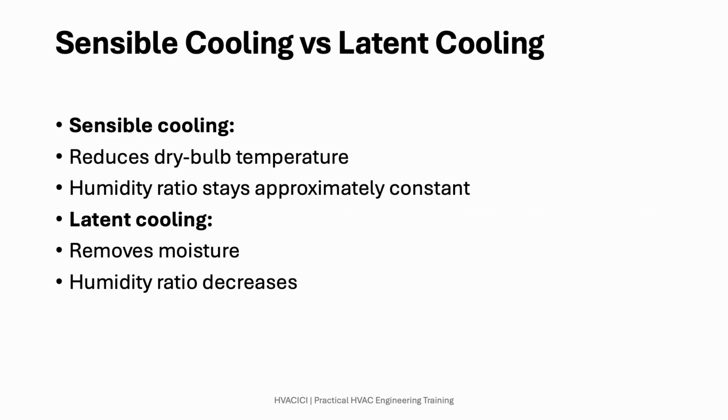If only dry bulb temperature decreases and humidity ratio stays constant, that is sensible cooling. When the humidity ratio decreases, moisture is being removed and latent cooling is occurring.